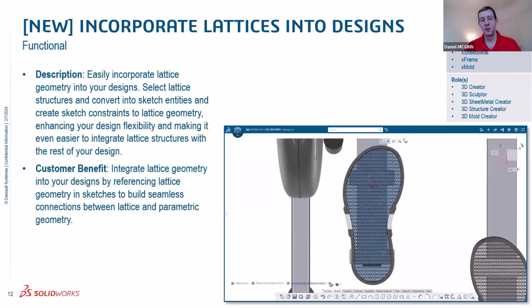Okay, continuing our theme of enhancements with lattice design, which we've been doing for the last couple of FDs. Now you can more easily incorporate lattice designs into your XDesign assembly or into a part with the ability to reference lattice entities in a sketch. So you can either convert entities or you can dimension or add constraints to lattice geometry from a sketch. So that's going to make it a lot easier to integrate lattice geometry into your designs.